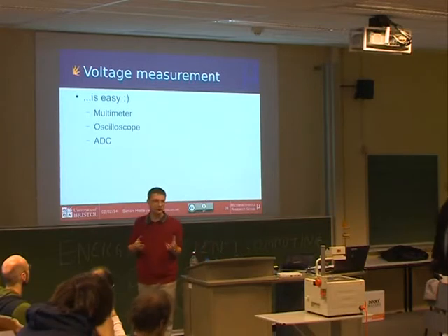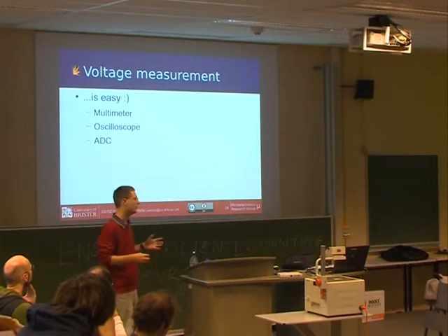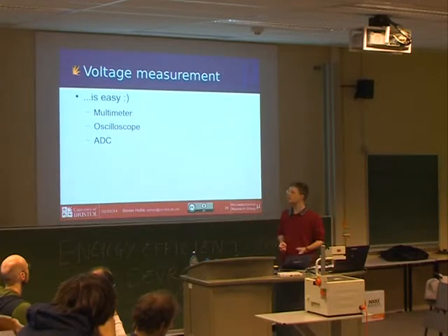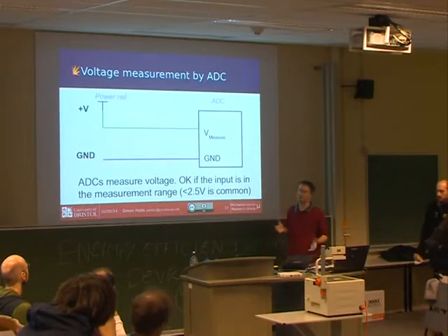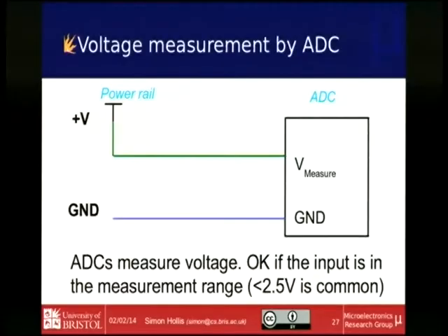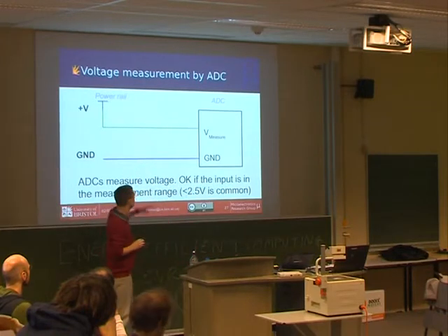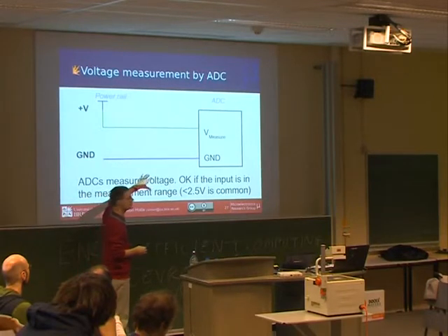The strategy we use is to use a thing called the analog digital converter, which is built into a very large number of off-the-shelf devices in the embedded space particularly. And we can make use of an ADC to measure voltage. So here's the high-level block diagram. The ADC is a block of a microprocessor, like this ARM-based microprocessor we have on here. Atmel, any vendor you can think of produces this, FPGAs, everything. So you apply a voltage in to an input to the ADC, give it a reference, ground, 0 volts, and it measures that voltage for you.